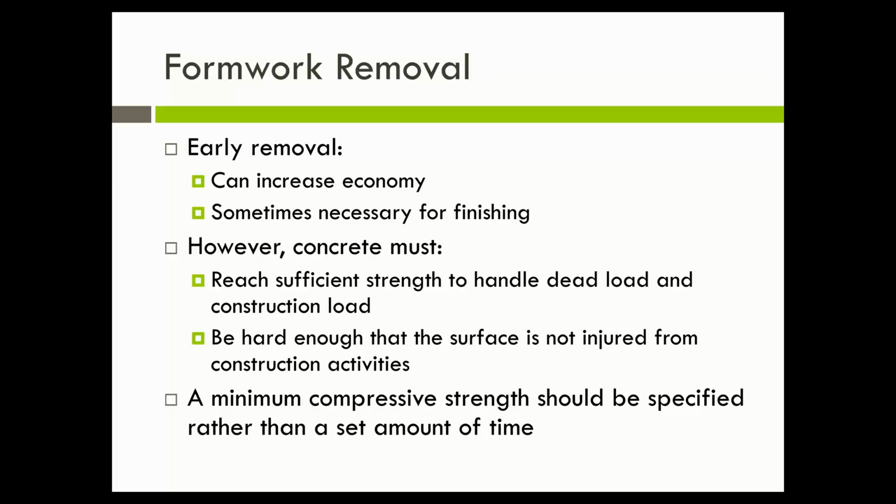One of the reasons that we need to cure our concrete is because we often rely very early on the strength. Even if we are not going to need our strength until 28 days according to the documents, we may find that we want to remove our forms and that the structural engineer or someone else is going to give us the guidance that says you can't remove the forms until you've reached 85% of the specified strength. 85% of the specified strength probably takes 3 weeks if you're going to hit the specified strength at 28 days.